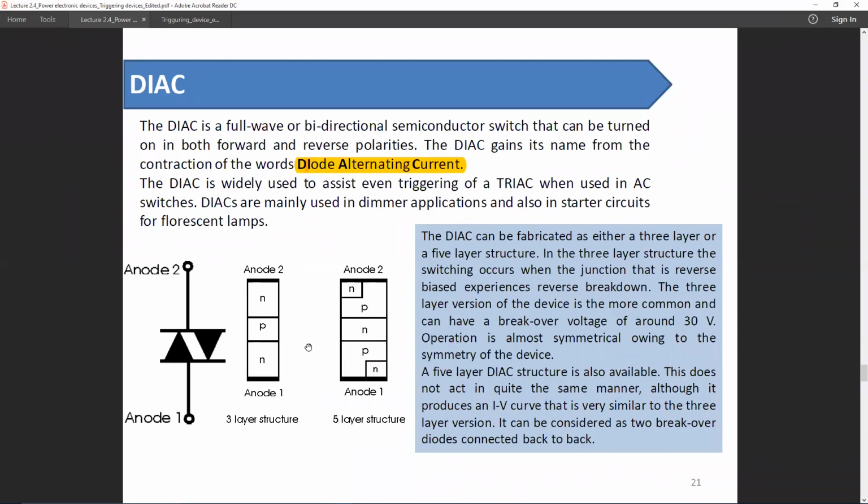If the value of the AC voltage is high enough, this reverse junction will be subjected to a breakdown. This type of DIACs are designed to operate in the breakdown region. They can eliminate the heat generated from this breakdown. Hence, there will be no device destruction.